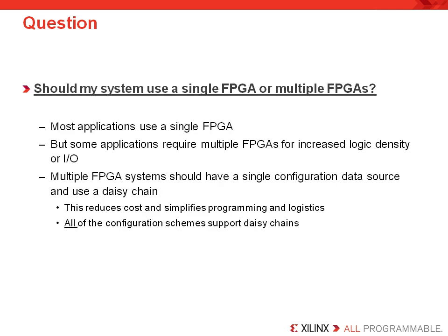Should my system use a single FPGA or use multiple FPGAs? Well, most applications only need one FPGA. That's because, of course, the density and the pins for the newer devices is so large. But some require more pins than are available in a single package or more logic than is available in a single FPGA. In those cases, the user should plan on building their application with multiple FPGAs and use a single data source for storing that bitstream.